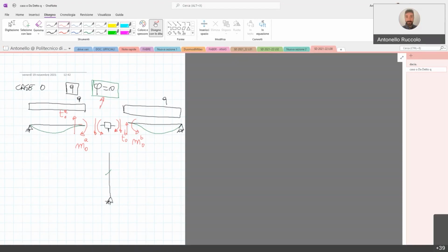internal forces diagrams, because the superposition principle applies for everything. We have already seen it with the force method. So if we know the values of the internal forces that are acting on the beam for each load condition, then we can also immediately use the superposition principle also on these internal forces. And so we will obtain directly the diagrams of the internal forces.